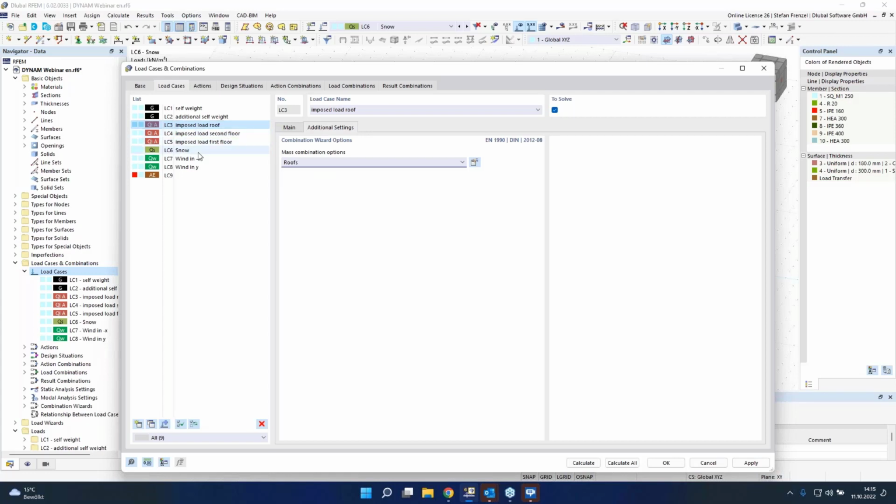And that means that the loads which you import could be smaller or could be bigger. Yeah. And here you see that we have, of course, the additional setting for our load for the roof. Of course, we say that's the roof, yeah. And for the second floor and for the first floor is another floor. If you use here, of course, also the normal standard Eurocode without national annex, you have here also these values and have also some different values for that. So that's just in Germany that you have here, of course, roofs or other floors.